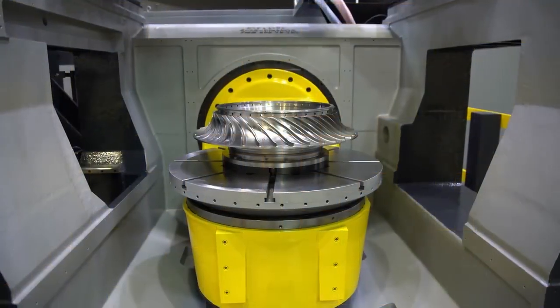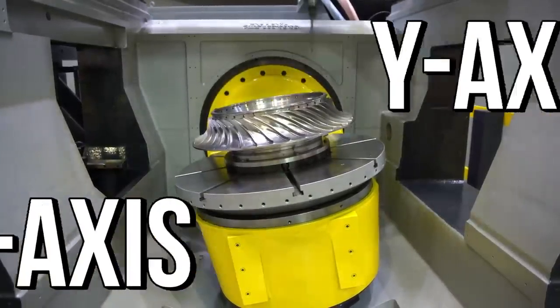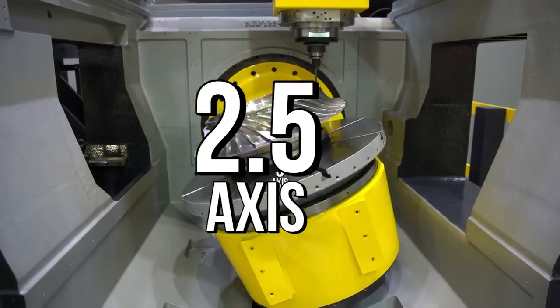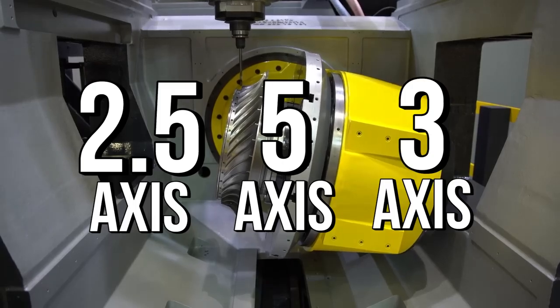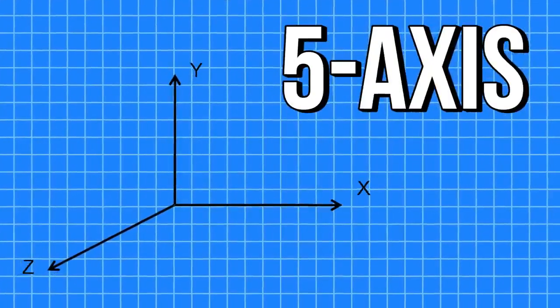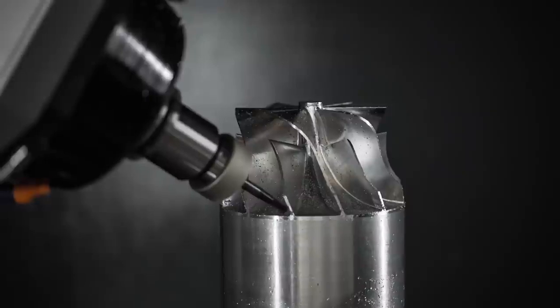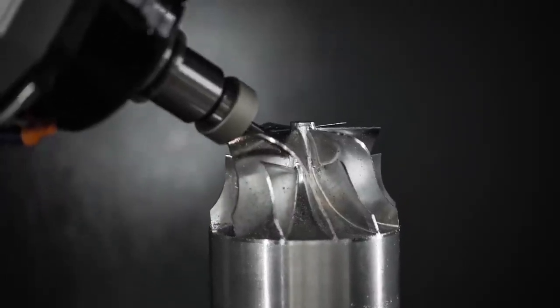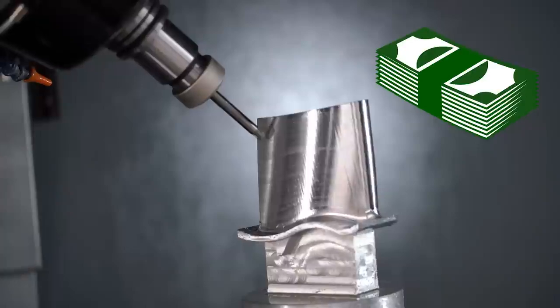Basic CNC machining will move one or two axes, referred to as the x-axis and the y-axis. You'll often hear the terms 2.5-axis, 3-axis, and 5-axis CNC machines, which simply refer to the degrees of freedom a machine can make cuts in. A 3-axis machine will move in the x, y, and z axis, whereas a 5-axis machine can move in these 3 axes along with 2 additional rotational axes. As you might be able to imagine, the possibilities of production with 5-axis machines are practically endless. 5-axis machines used to be relegated to high-precision work, but as they have become more affordable, they are quickly becoming standard in many shops.